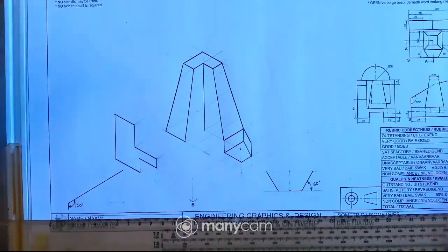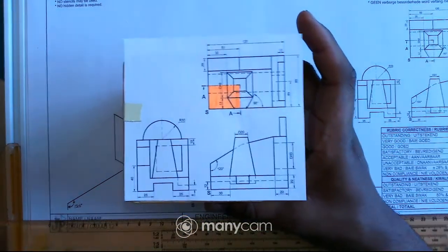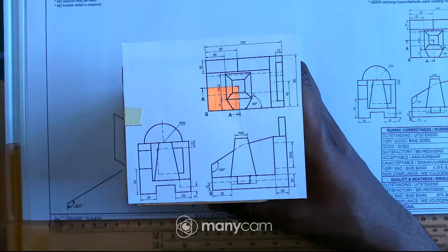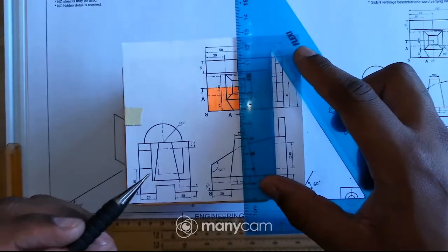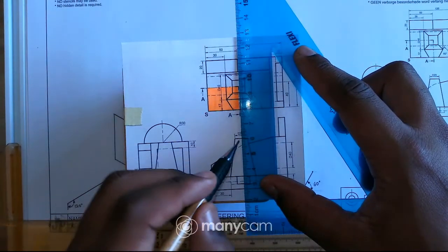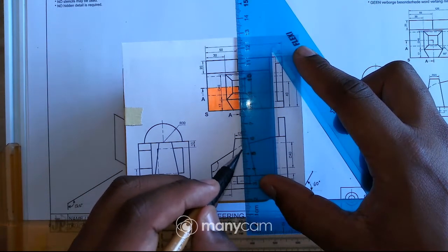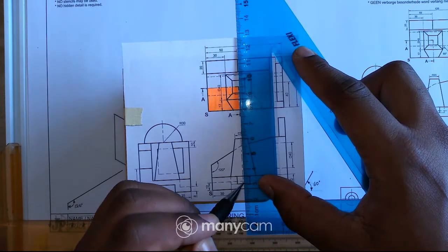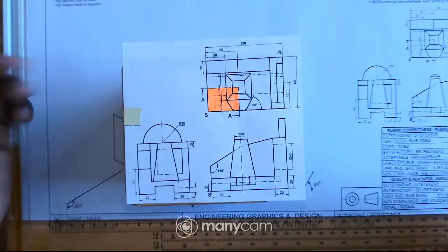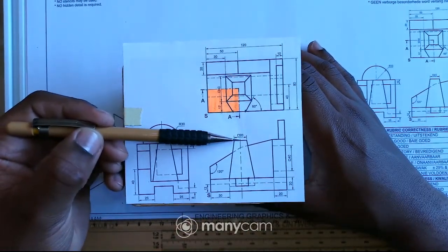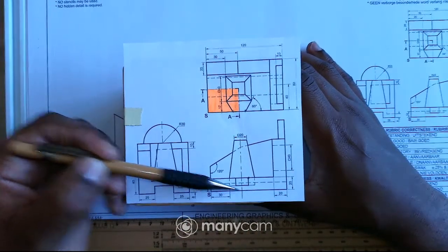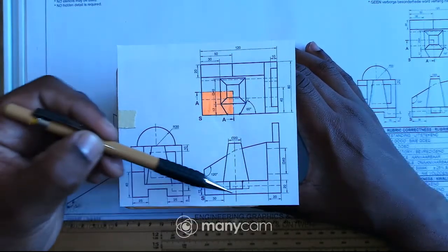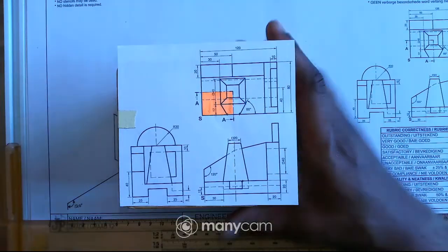Okay, so now I can draw this L-shaped surface, this one. Obviously, let me just do like this. The cutting plane is right there, right? So I can just add a cutting plane on our front view there. So it's like we have cut this object there, right? That means I'll only draw this surface only, and then this one obviously is cut out.